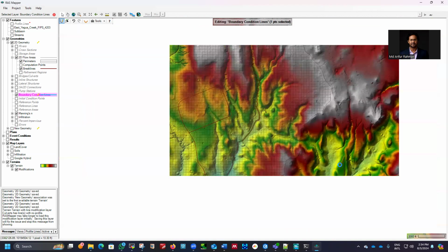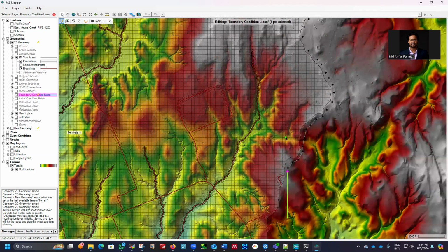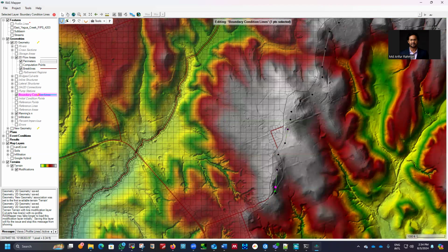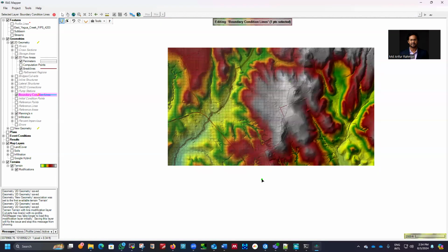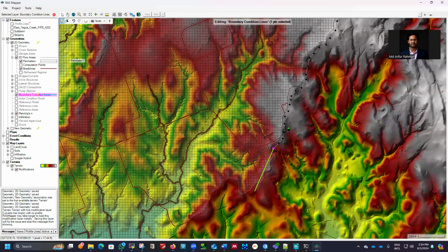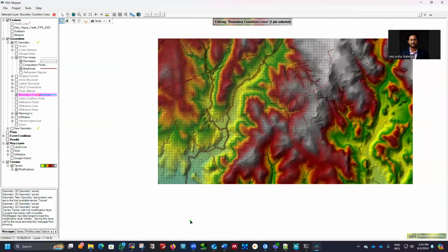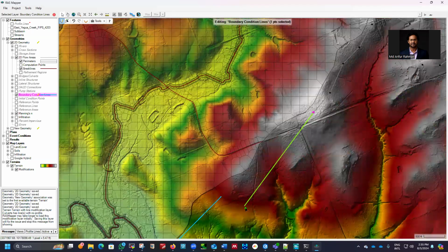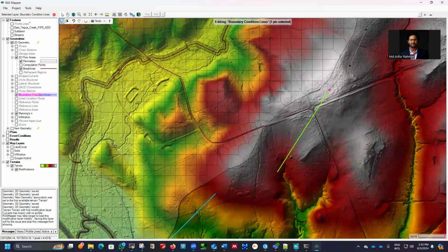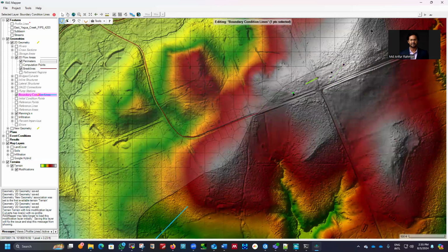If you are familiar with steady and unsteady conditions, you know that if the hydraulic condition, like flow velocity, changes with respect to time, that means it's not constant, it's not steady, so it's going to be unsteady. So we are going to run the model for several days because we already created the rainfall data. We distributed the rainfall over 24 hours, and we have a 6-minute interval for that grid. We already saw that in the previous videos. That means we have different values with respect to time, and it's going to be an unsteady condition, so that has to be correct as well.